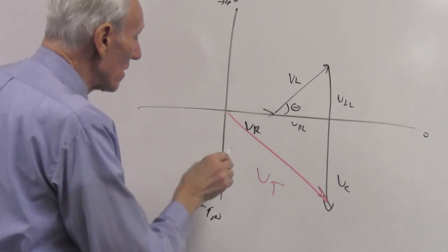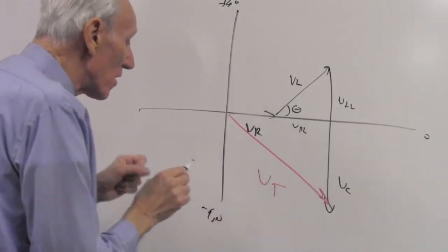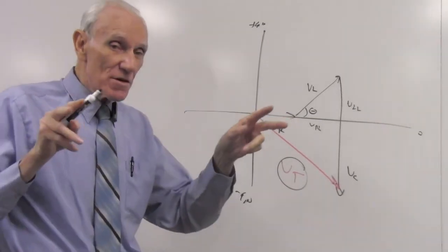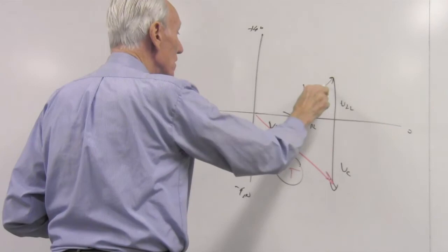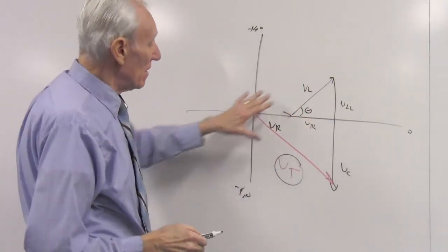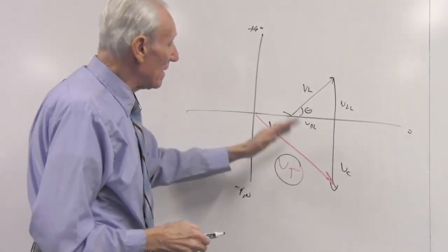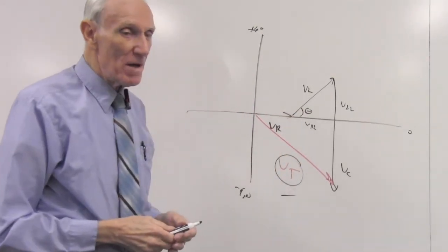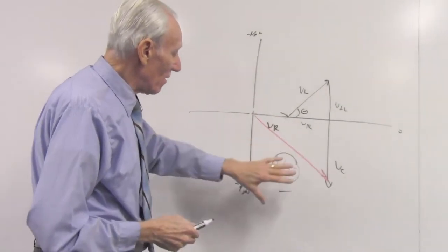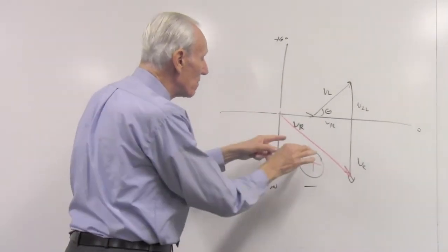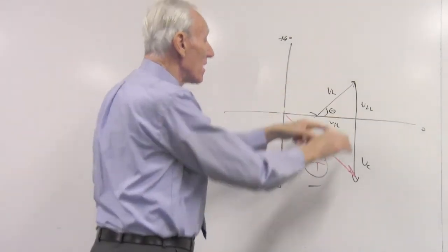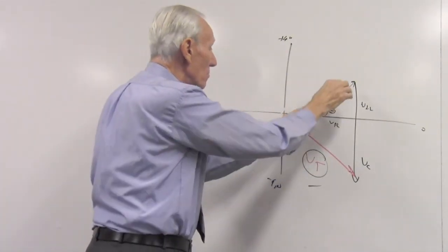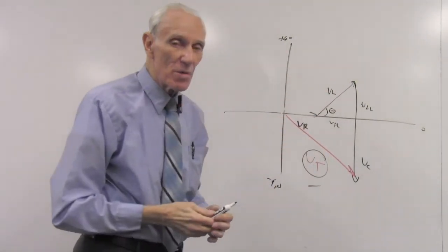And so we can get the overall phase angle here, but the question is, is this total voltage the vector sum, so to speak, of this voltage plus this voltage plus this voltage, drawn at these angles: 0, minus 90, and whatever that angle is in part B. So that is the big question. So check that out, see how close you come to your measured voltage being equal to the calculated voltage from part A and from part B, and also together from part C.